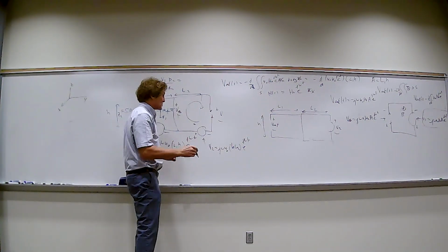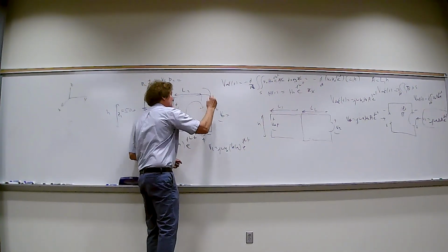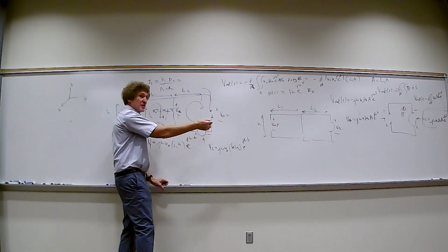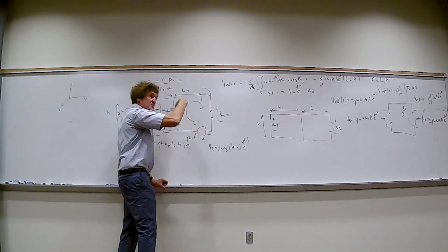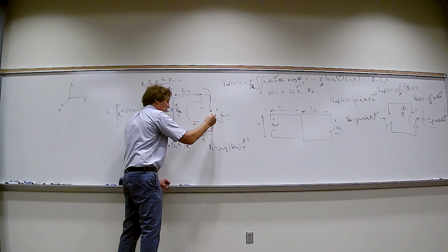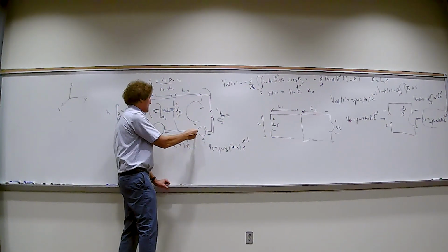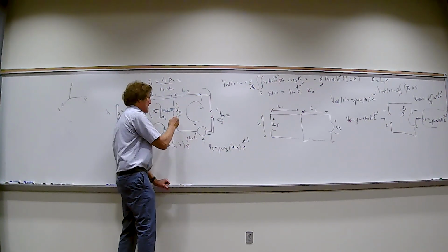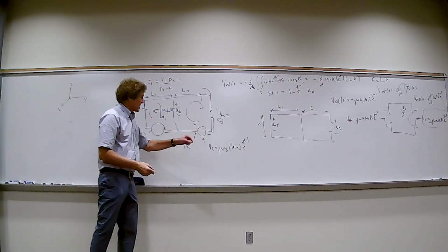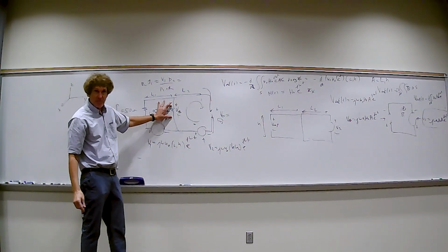Now, if you look at this, what is this voltage going to be right here? How much current is flowing? None, right? So if you want a voltage, how are you taught to do it? The sum of the voltage drops around a closed loop is 0. But the easy way is to start at the negative terminal and go around here. You get an increase of V2 here, and keep going. You get an increase of VR2, and then you're over here. So that voltage right there is just the sum of that voltage plus the voltage developed there. You all see this, class?